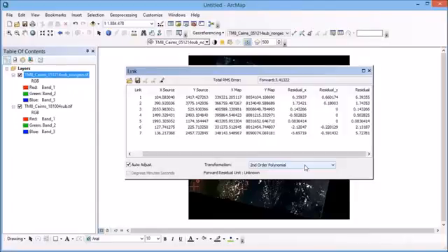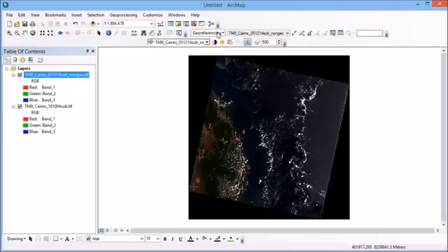So when you're collecting these ground control points, the next thing that you really need to make sure that you do is to save. So you can save these ground control points. If your project crashes for whatever reason, you can always bring them up again and then reapply the transformation to finalize your georeferencing, if that's what you need to do. So you can kill that table and it doesn't make you lose your points at all. It just pops them out of sight.